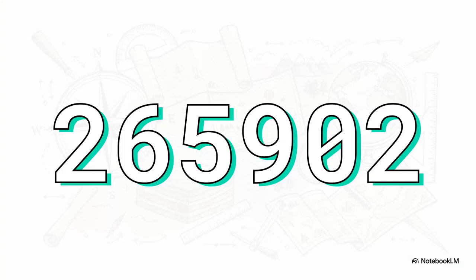For that specific temple near Kedah, the magic number is 265902. Let's see exactly why. The main easting line to the temple's left is 26. Mentally dividing the square, the temple sits exactly halfway, or 5/10 across the grid, giving us 265 for the first half of the reference. The main northing line below it is 90. Mentally dividing the square vertically, it sits roughly 2/10 up from that line, giving us 902. Merge them together, eastings first, northing second, and you get the precise code, 265902.